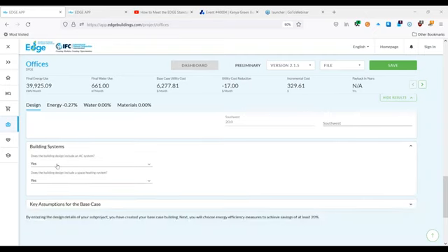You can say whether the building has AC systems or not. In this particular project, if it's an office building in Nairobi, we would like to design ideally for no AC system and obviously no heating system, in which case we'll put no here. But if you were designing with AC systems, you would select this, and you'll see why when we move into the energy tab.